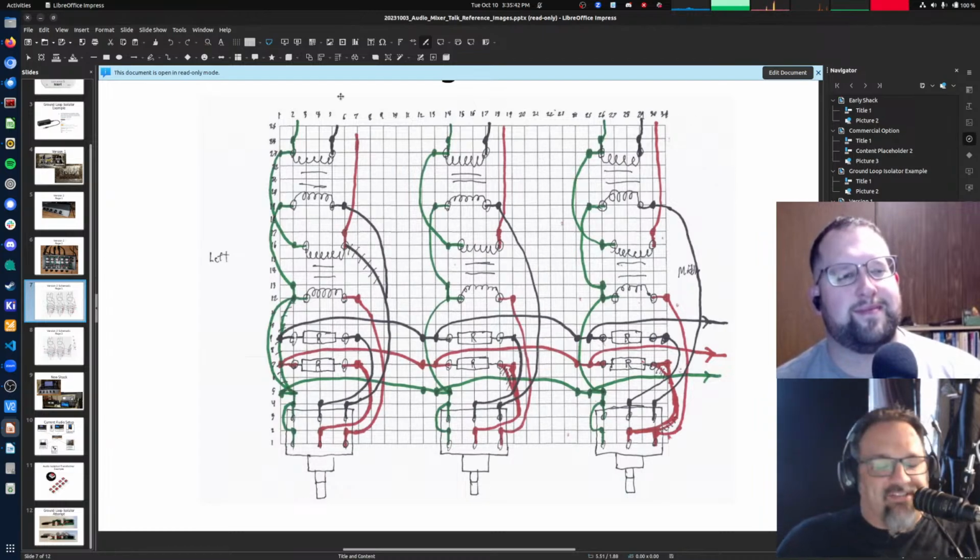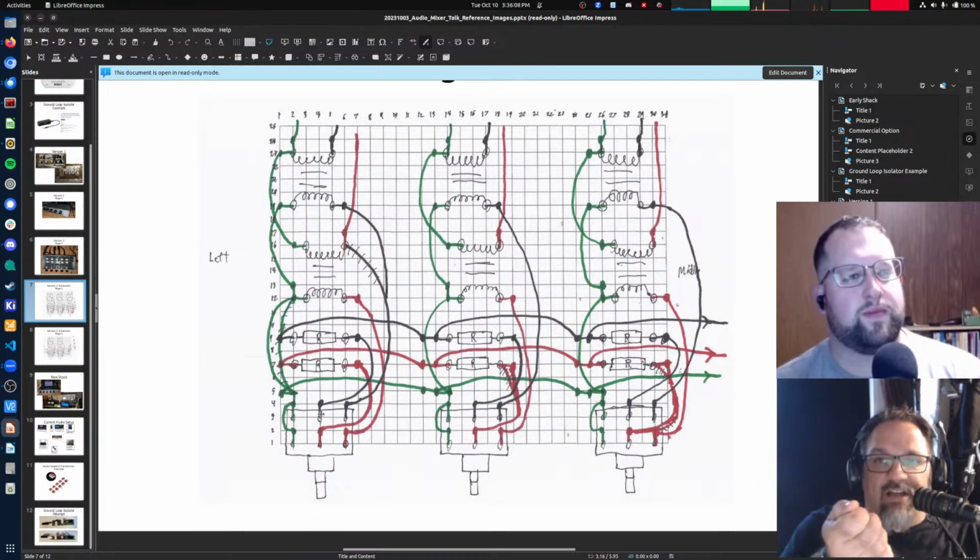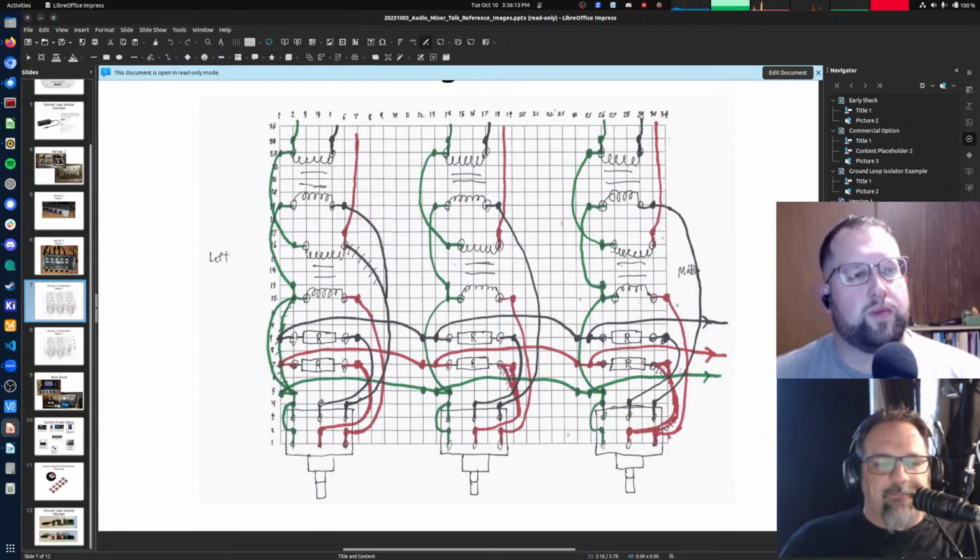So all right, this is what's happening here. You've got a signal coming in from one of your devices. Let's say this is your 7100. It comes in through the transformer, gets isolated, and then comes out from the transformer into your potentiometer. There's some amount of resistance between the input to the pot and the wiper of the pot. More importantly, there's also some resistance between the wiper and ground. It's not turned all the way down. It's somewhere in the middle where you can listen to it. This goes into the series 1K resistor here, and it goes into the common bus out to your output.